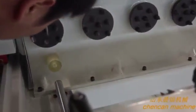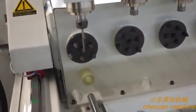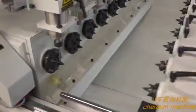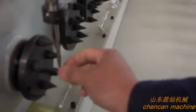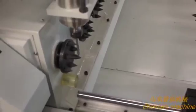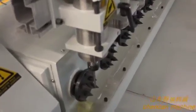Almost there. Now we check it. Now the tool center is in the rotary center. So now the Y. Its touch is this center.